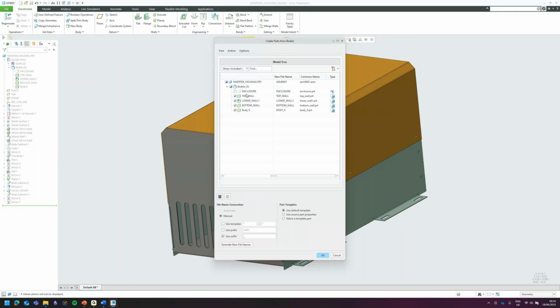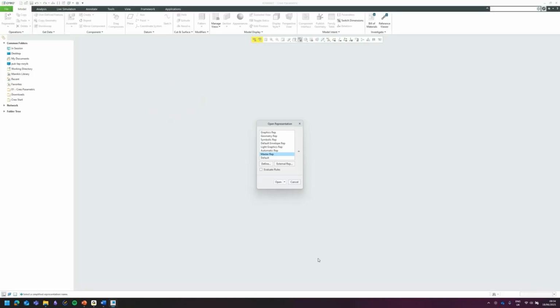I don't need that. And for sheet metal components, we can also pull through the inherited information, which is going to give us that feature list. Again, slight caveat there for working with inherited features: Advanced Assembly is required to go back and make any modifications to that. But I will show you some of the differences here. I turn one to a copy geometry, so at least you can see the differences. Obviously, renaming conventions are fairly standard throughout Creo Parametric, but let's create this assembly.